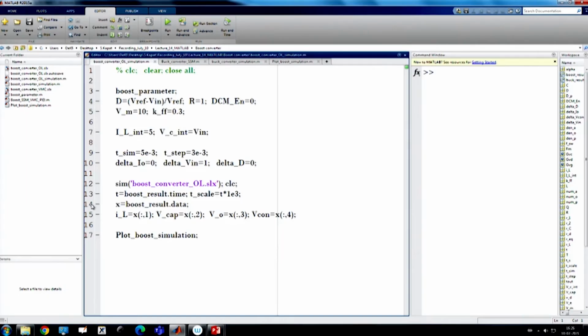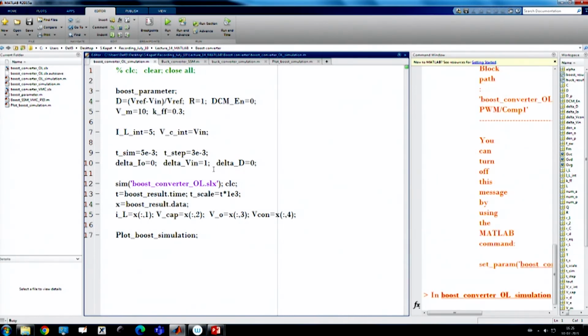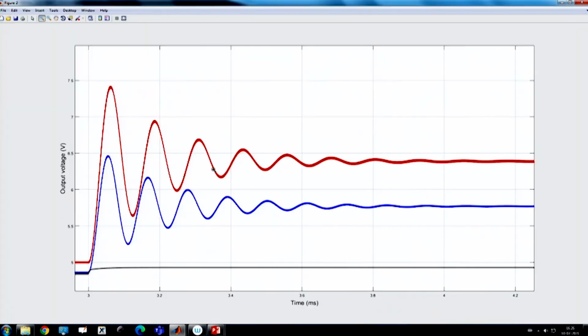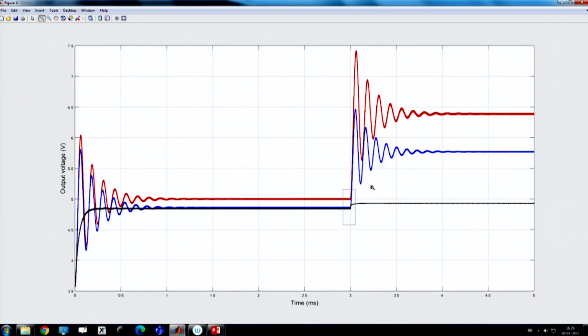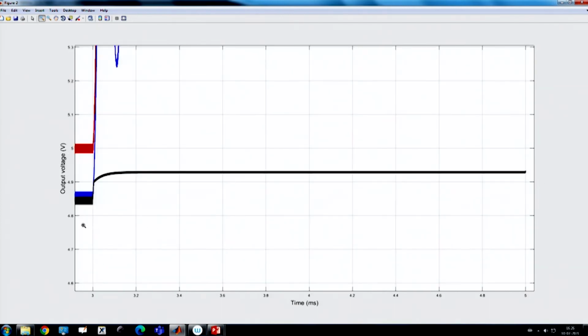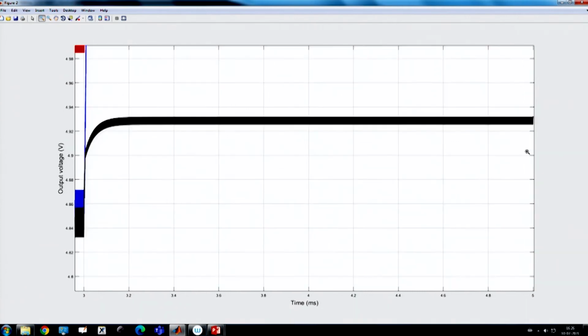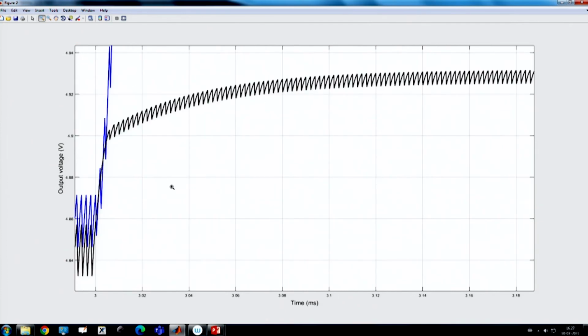Now, if we simulate this case and compare what happens when we connect the inner current loop whose reference is generated, you can see the effect due to supply variation is drastically reduced by this technique. This is also a kind of feed forward technique, but we are only considering the current loop. You can see there is a shift in the DC because we are setting the current reference, not the actual average current, but just the peak current.